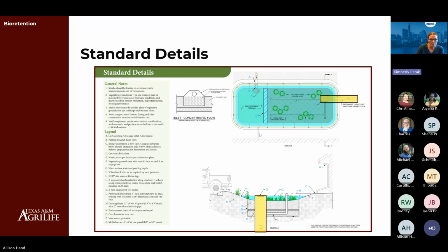Okay. We also want to make sure that we perch that underdrain system into the section a little bit, to give the opportunity, if there are any infiltration opportunities, for that water to draw through the system before it immediately goes to the underdrain system. And the underdrain system ultimately would be tied into the outlet structure as well. And like we saw on the other design sets, that outlet structure you need to design for your ultimate design storm. So typical local criteria will set the design storm, and so you want to look to your local criteria for that. But it's typically between a 25-year and 100-year design storm, where the top of the elevation is set to your water quality elevation.